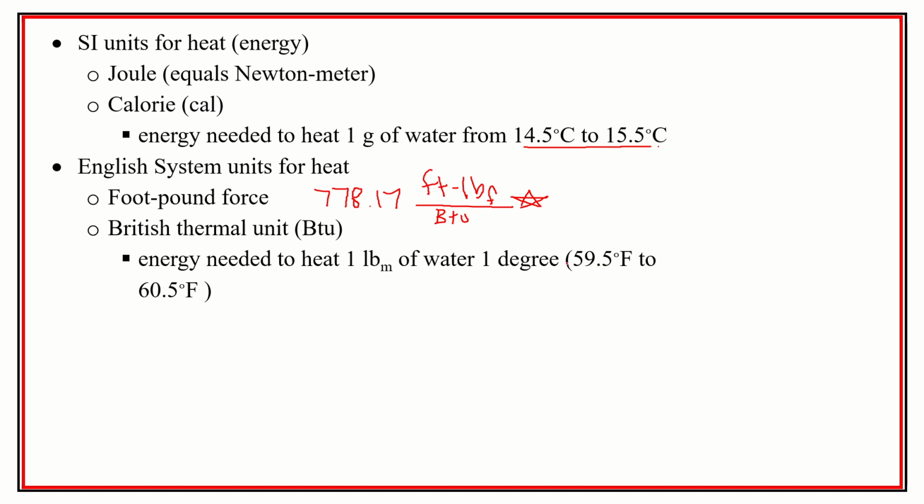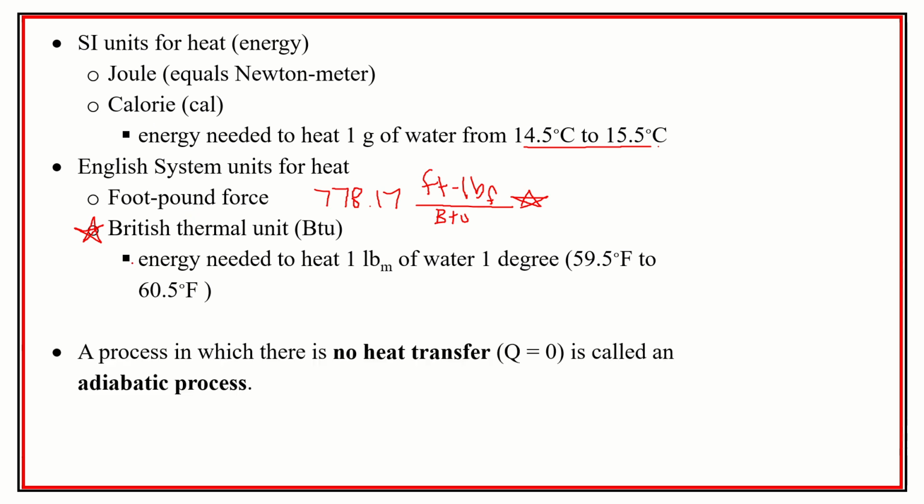So just be aware that when you think of a BTU, it's going back in time, but still used. This is sort of an ancient but still used method. And here's how they came up with it, right, as the definition of what a BTU is, so you can kind of maybe picture a pound of water in 1 degree. And that's very much related to the calorie in the SI units, which gets used sometimes, but not most of the time. We're dealing with joules, or kilojoules, actually.